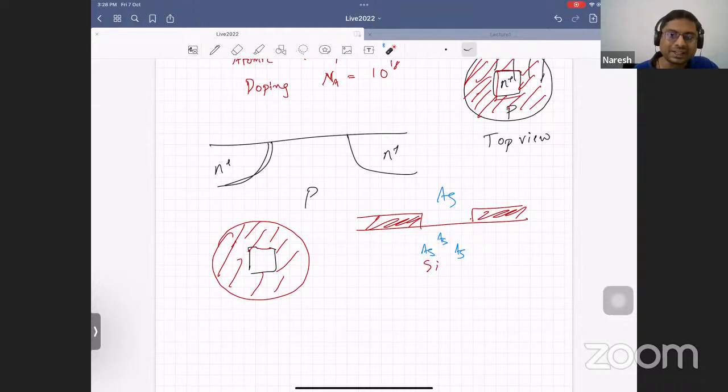So with this, we can actually implant much better. Much higher densities can be achieved. That's why we have moved towards implantation most often, especially in the device front end of the line. I think it's implantation. Diffusion is, yeah. All right, I hope I answered your question.